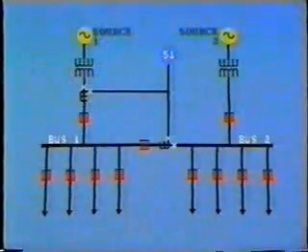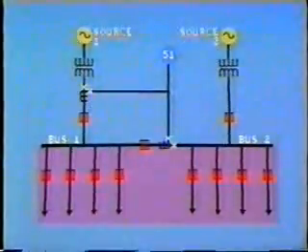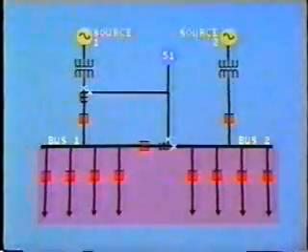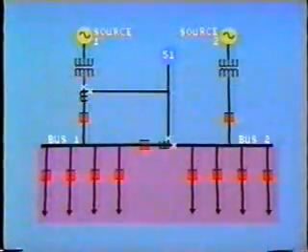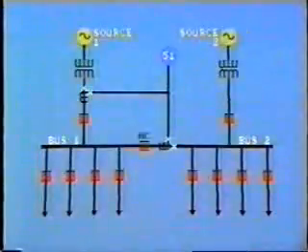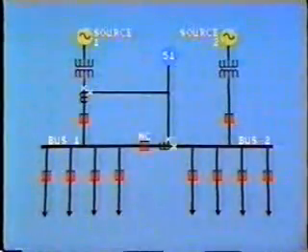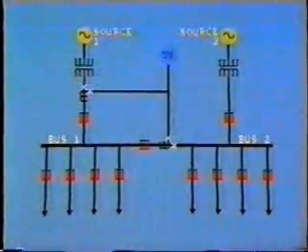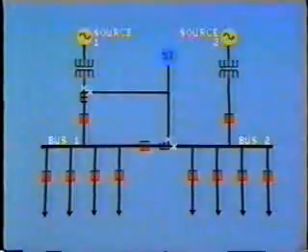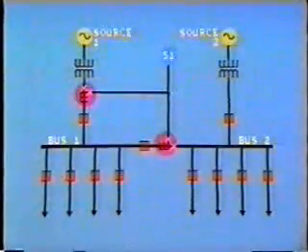The buses are fed from two separate sources and feed 8 outgoing radial feeders. As the feeders are radial, the current will not reverse in the case of a bus fault. On this particular system, the bus tie is normally closed. Partial differential protection for bus 1 is provided by the time over current relay 51 connected to these two CTs, which are in parallel.